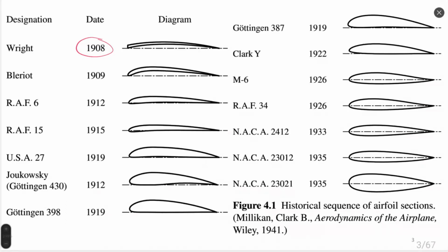Why do different airfoils exist in modern aerodynamics? The main reason is that airfoils operate in different conditions and are built for different applications. There is no universal airfoil that would work perfectly in all types of flow, in all conditions, for all applications or velocities.